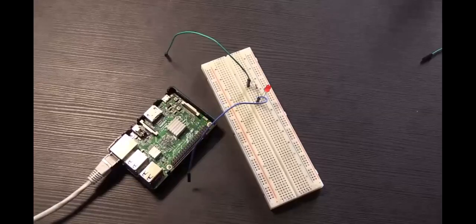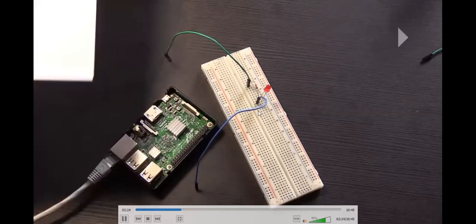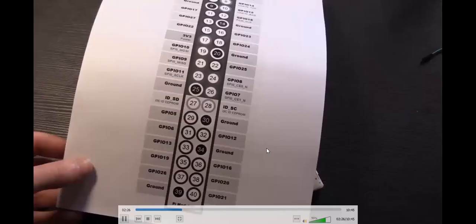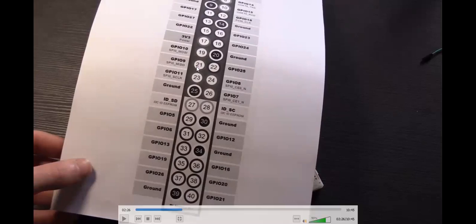So, exactly where are we going to plug these in today? So you may notice that he used a male to female cable, because in Raspberry Pi we have male pins. So we have to use these kinds of pins to connect. GPIO pin number 5. So if we look on our handy little chart. So I told you to print this kind of chart, whatever the Raspberry Pi you are using. We have to obtain a printout.